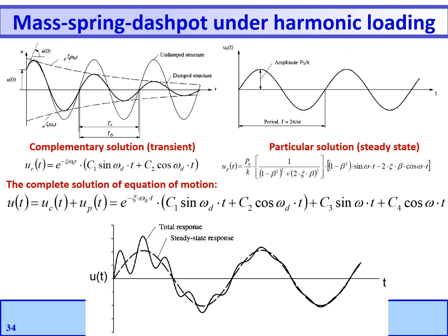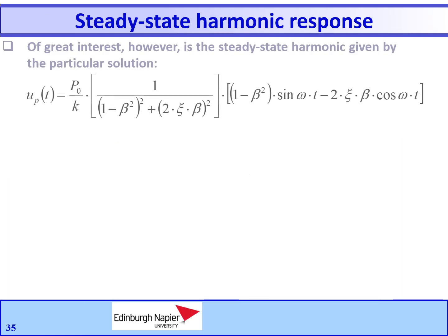After a while, essentially the forced response remains, which we call steady-state response, and this will be our main interest from now on, although it should be recognized that the largest deformation peak may occur before the system has reached the steady state. As explained from the previous graph, the forced response essentially remains, so we are particularly interested in rewriting and working with this, just the steady-state harmonic.